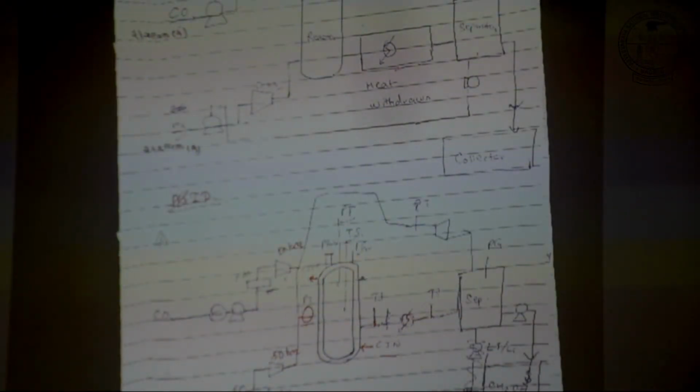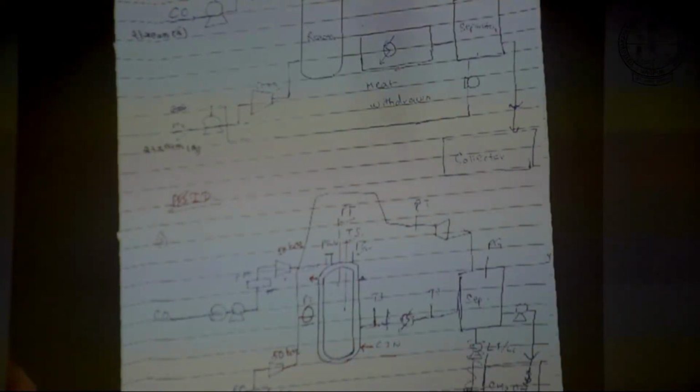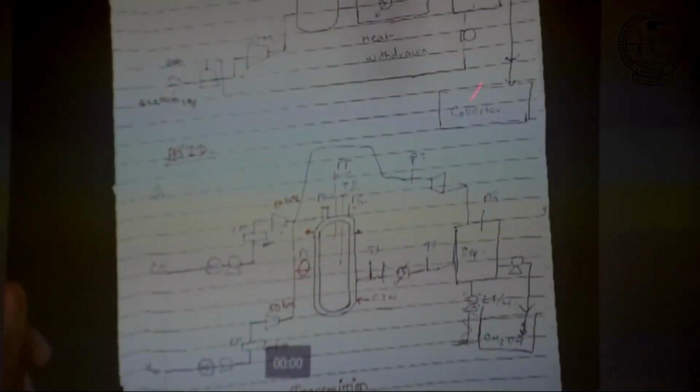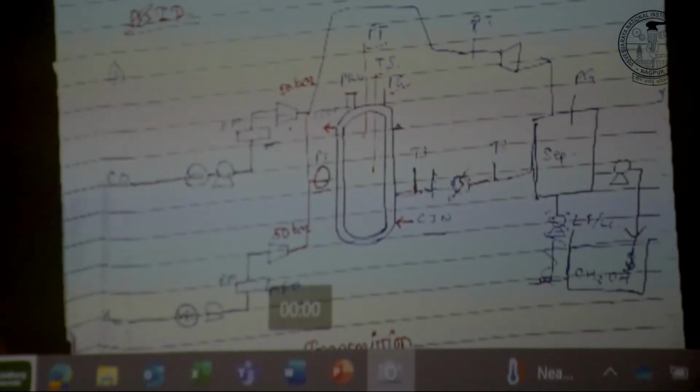Thank you, sir. So comments once again from other groups. If you can turn the page on the PFD. What was really good is that they thought about all the equipment. They started with the reactor, and across the reactor they thought about separation. You remember this onion model: you start with the reaction system, then separation. Probably they thought about utility. But maybe one small comment: you probably missed the heat integration.